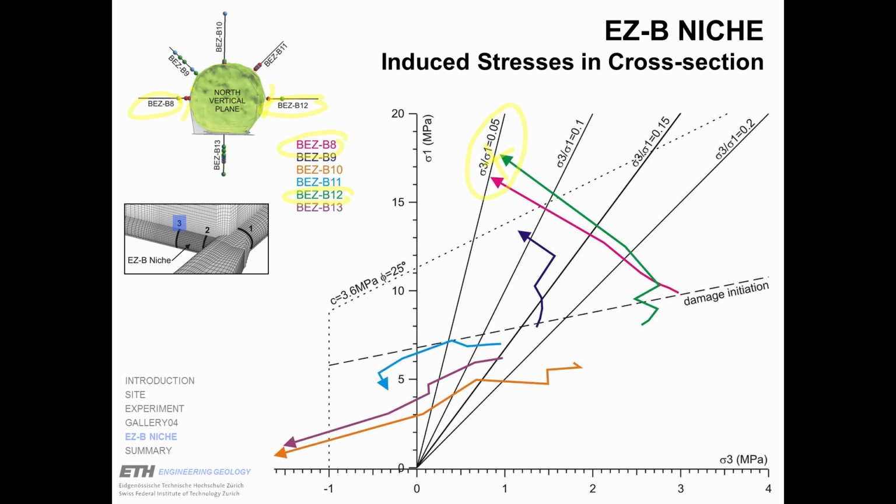And when you are more distant away from the excavation boundary, we still have some damage which can only be seen in seismic properties and which relates typically to spalling ratios between 0.2 and 0.1.